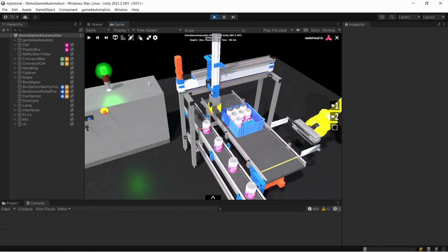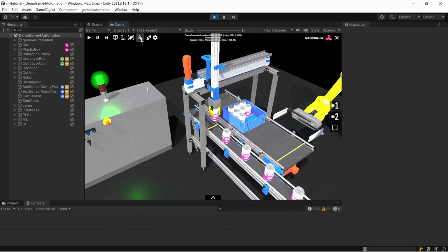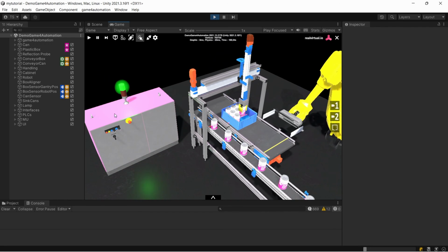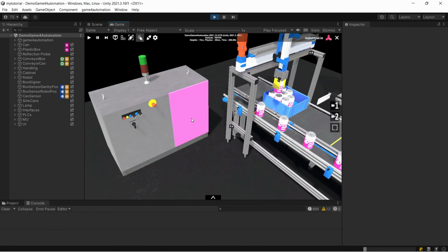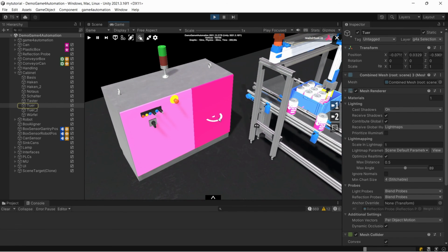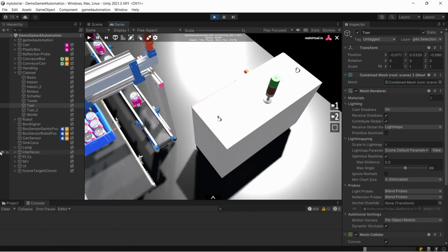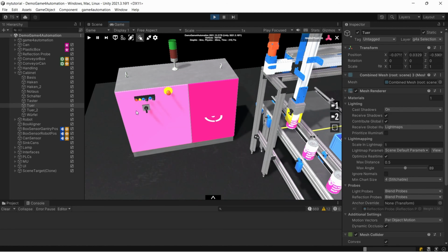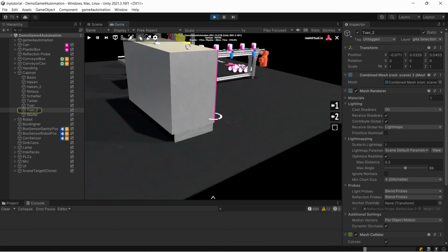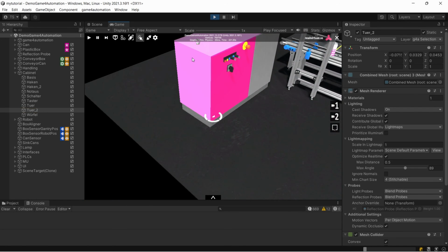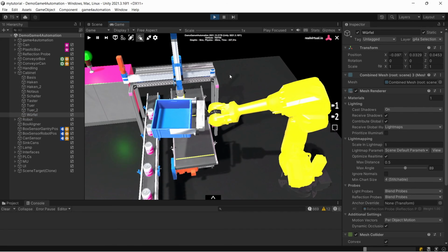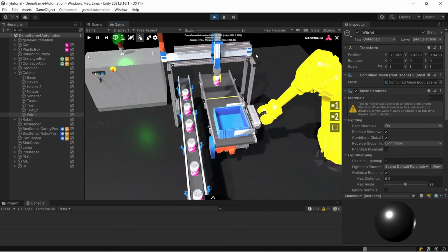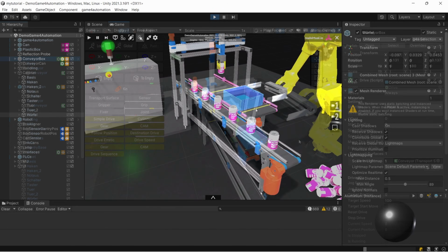Another thing which is new in the latest versions is that we can have a selection mode here. In the selection mode, things are highlighted, 3D objects which are detected by the mouse. And if you double click on it, you will get a rotation point set here on this component, and you can rotate around this component, or let's set the rotation point down here. By double clicking, I'm setting this rotation point and focusing the component. By pushing escape, the selection is reverted.